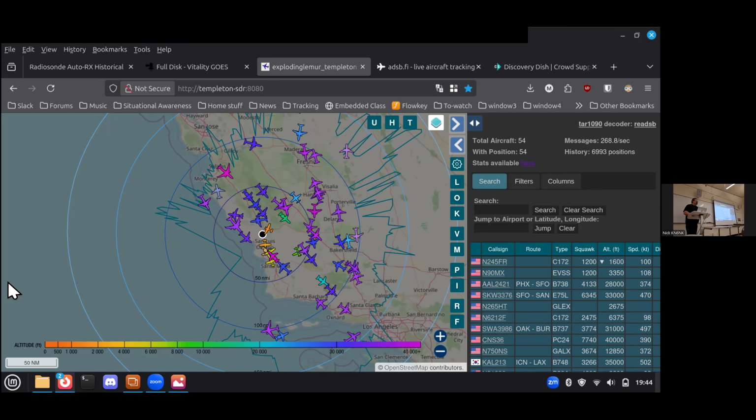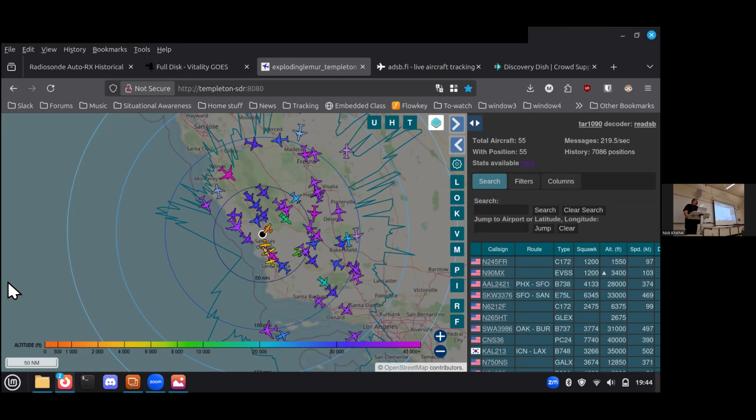When you say blow out your SDRs, do you mean the transmitter would damage them? If it was powerful enough, yes, but generally it's just going to overwhelm them so that the only thing you see is the signal that you're transmitting, no matter where your SDR is tuned, unless you have a lot of very narrow filtering in front of it.